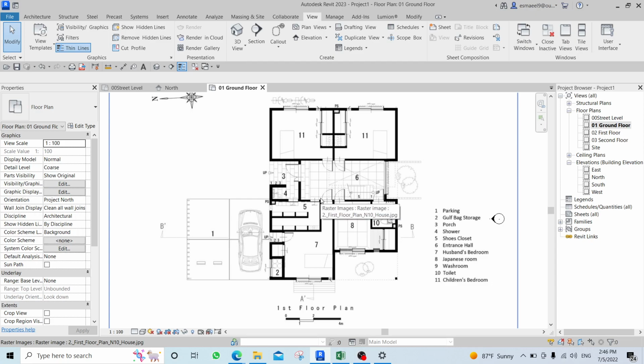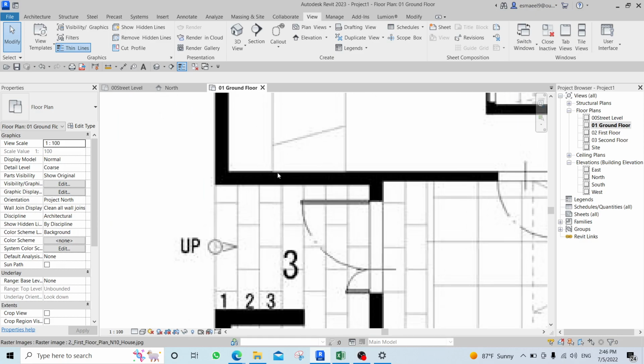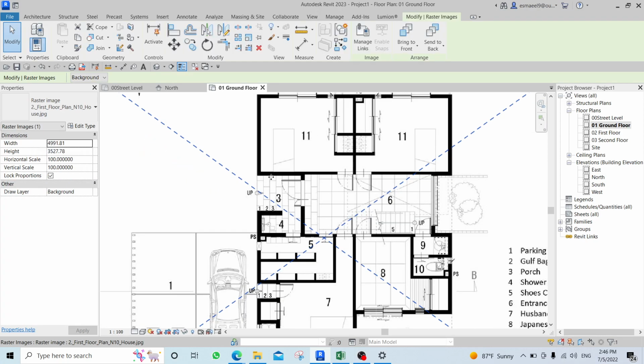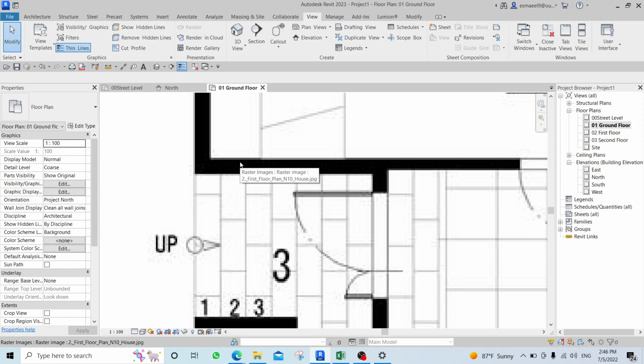Now, the process of creating or just preparing this image. Please, when you are making your exercise, since this is gonna be your homework, guys, follow the exact steps I am doing now. So I'm now zooming in in order to scale this image, because now I don't know the scale of this one. I don't know the scale of this wall. So if I just click on this image, or if I just click DI, I just want to be able to find or calculate or measure this distance, this thickness of this wall.